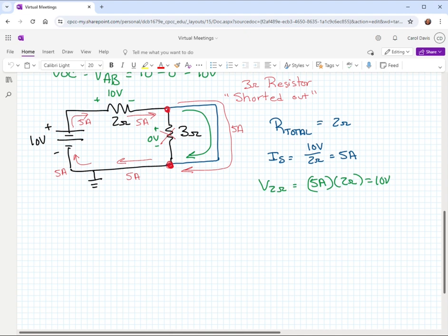And this is a problem because if you have, let's say, your load over here, this 2 ohm resistor, or maybe it's a light or a fan, maybe it's rated only for up to 3 amps of current. And now we've got 5. What that means is we're probably going to burn up the component that we have left and create an open circuit after that. So it's going to continue to create problems for us probably. Anyway, that would be the short situation.